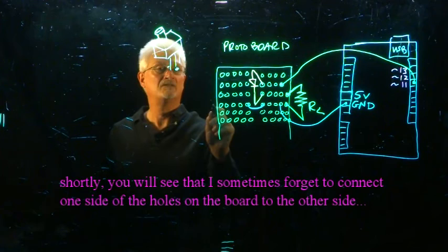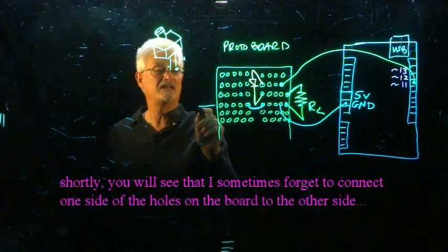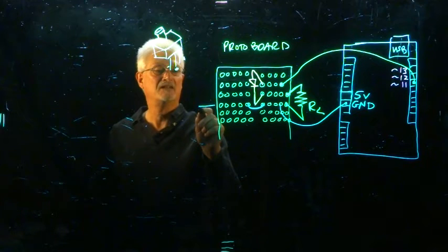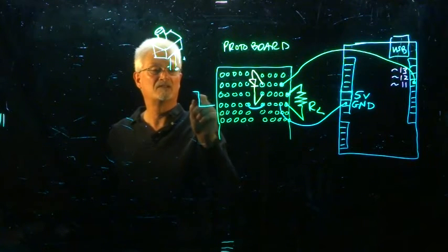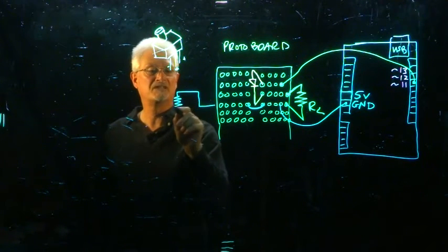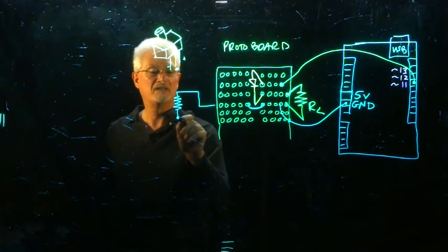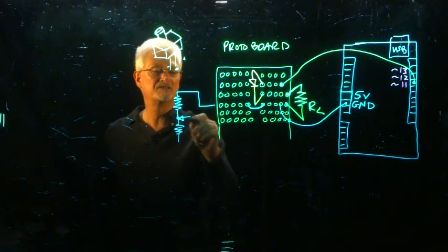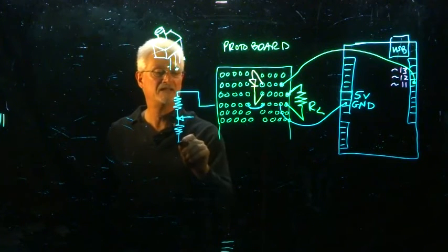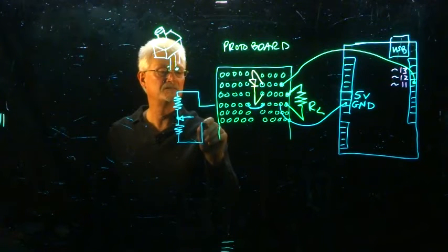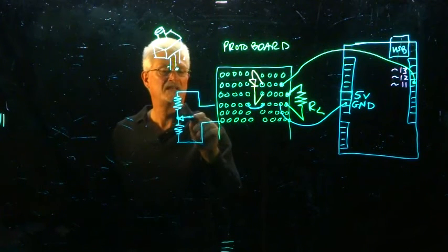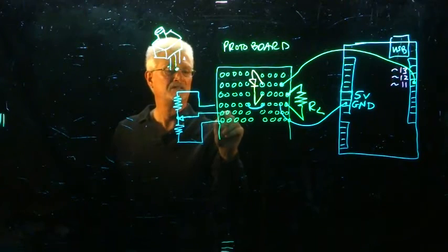And so now, maybe what I'll do is put my potentiometer this way. Now I'm going to have it upside down, but that's okay. You'll be able to figure out what I'm doing with it. So here's my potentiometer, here's my measurement, and this is my wiper. So I'll put an arrow on the wiper that shows that it can move up and down. And then I'm going to put this to the positive, and I'll put this one to the center one.